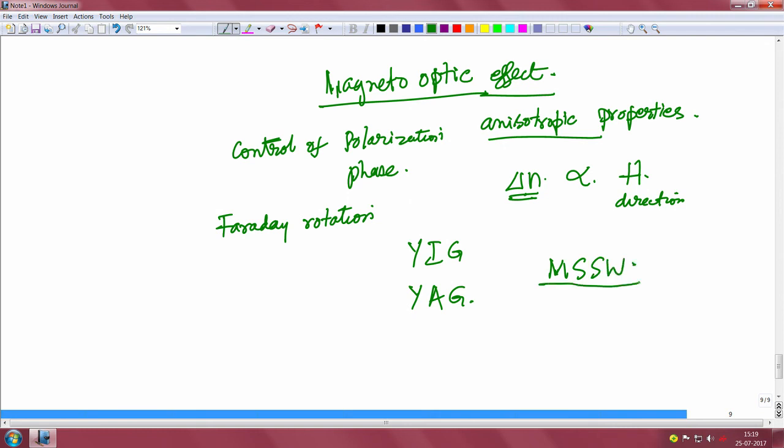So, magnetostatic surface waves could be created and propagated on magnetic crystals like this, and some of them have good optical properties. So, you can have a good interaction between the electric and magnetic properties to achieve some good functions. A magnetostatic surface wave also could result in a grating-like device through which the light could be propagated. So, once again the magneto-optic effect could be a function of RF to create gratings and so on.